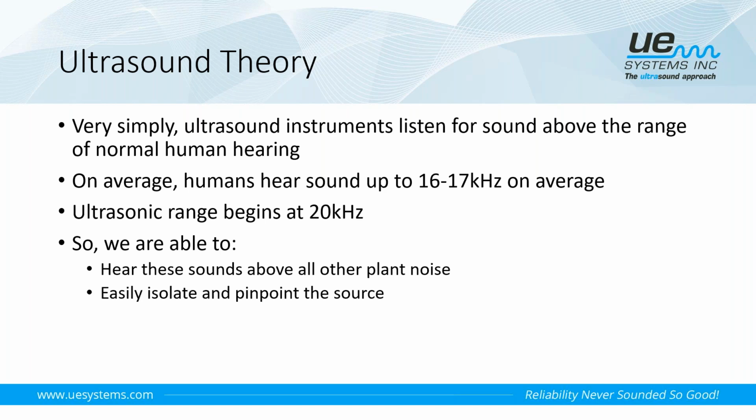Since we're only listening for high-frequency sound, it makes it very easy to isolate and pinpoint the source, even from extended distances away. So it's very easy to do. We can filter out these sounds to avoid false readings. There's an adjustment on the instrument called sensitivity. So, if you go through any of our level 1 courses, we spend a whole day on just the science and theory of how ultrasound works.